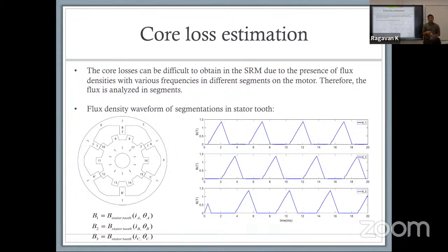However, what you don't get is iron loss. What about the iron loss? You still have to account for that. It's not as negligible as you'd want it to be, especially if you want to extrapolate that information to get it to thermal behavior.